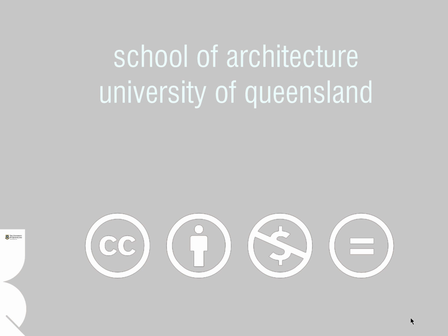So that ends the brief introduction to surface finishes. What we've tried to show is that a lot of the surface finishes, particularly nowadays, are achieved simply through off-form concrete, but one needs to be careful, and one also needs to reference the standard AS3610 to make sure that you convey your intention to the builder. There are other techniques where you can apply finishes to an off-form concrete, or use a mechanical process to roughen up or scabble the surface to disguise the imperfections.